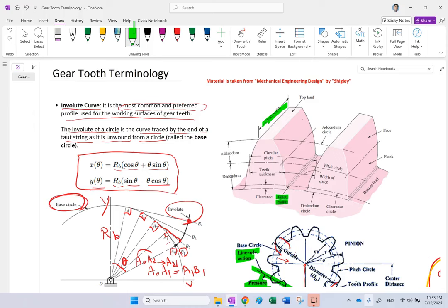So to reduce the stress concentration and increase the life of the teeth, what you need is to fillet all of these internal edges. And depending on that fillet radius, you have different concentration factor coefficients. So these two parameters will affect the life of the gears as well as, of course, the pressure angle. Okay, so you can see that as well.